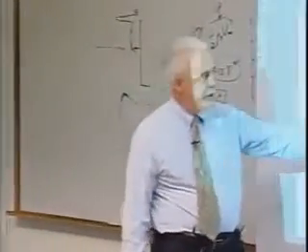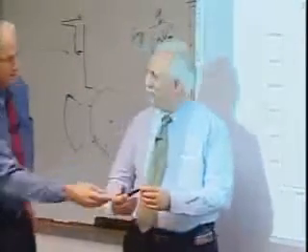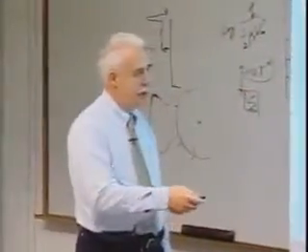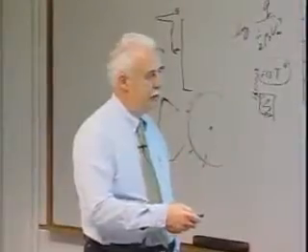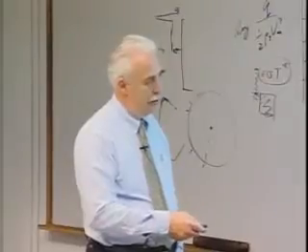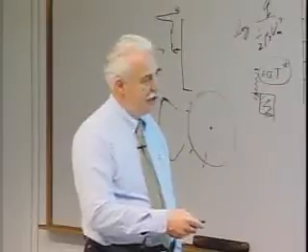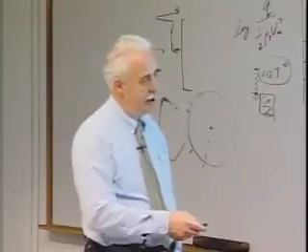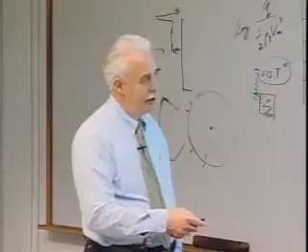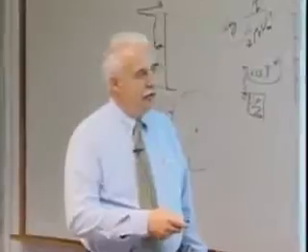What I've shown here is, first of all, this is 1 atmosphere total pressure. This is 1/10 of an atmosphere total pressure. And first I'd like to focus on the Apollo orbital return. And I'm going to show data from actually one of these flights. These bands are to show the flight regime. And this is the lunar return, coming back at 36,000 feet per second, and then essentially going through an orbital entry. So you can see there's an order of magnitude difference here.